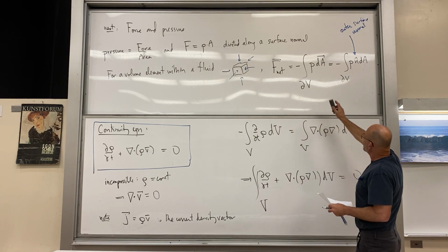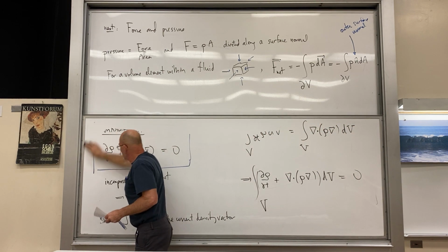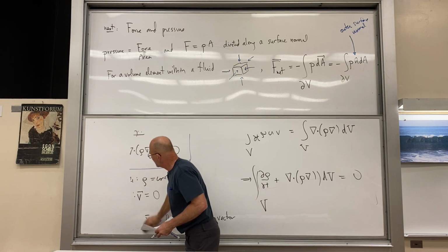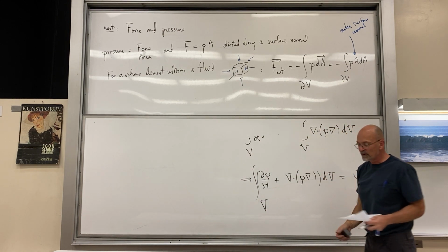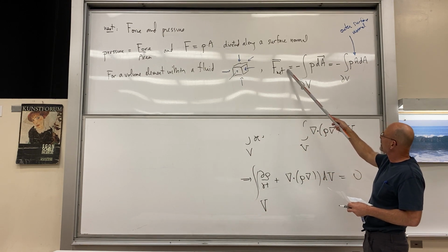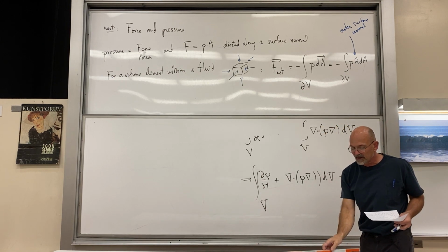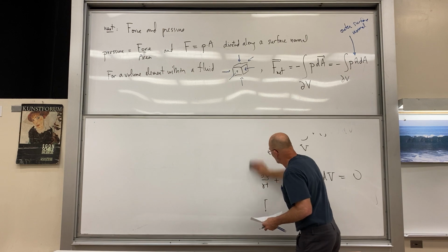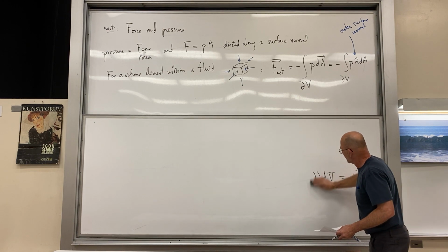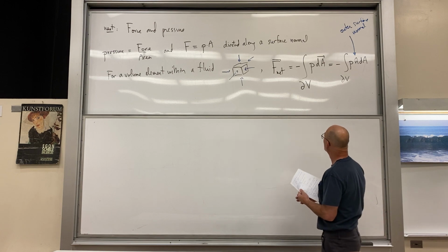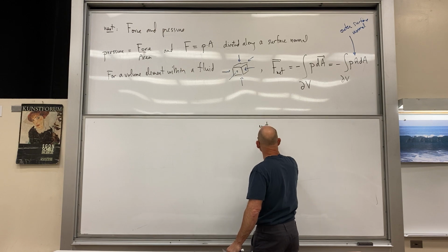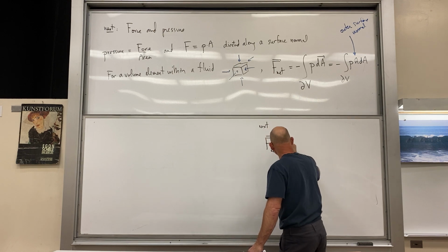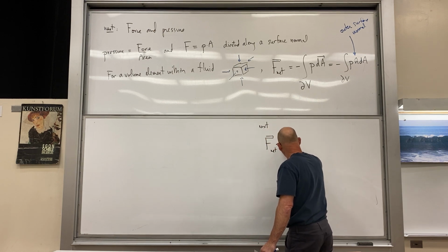So next is an interesting trick that we do on this. We're going to scalar multiply it with a unit vector. And we're using Cartesian vectors right now, so if we scalar multiply with a Cartesian unit vector, then we'll get the ith component of that force. So multiply F net, that vector, dotted into the x of I hat unit vector,